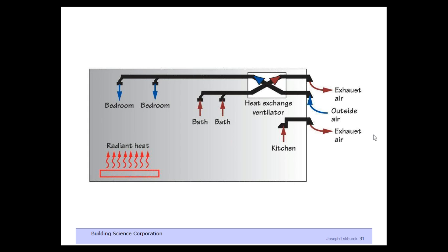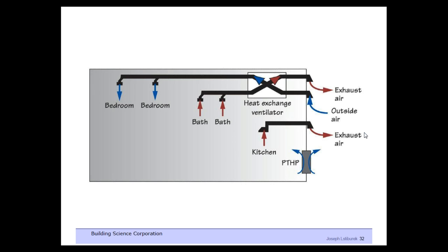We see a lot of this in the Pacific Northwest. The nub is that this won't work with the kitchen exhaust without having an interlocked makeup air system. As we go down the coasts, we're finding that people are adding package terminal heat pumps. That provides both the heating and the cooling. HRV, ERV, pretty slick system, but the problem child is still the kitchen.